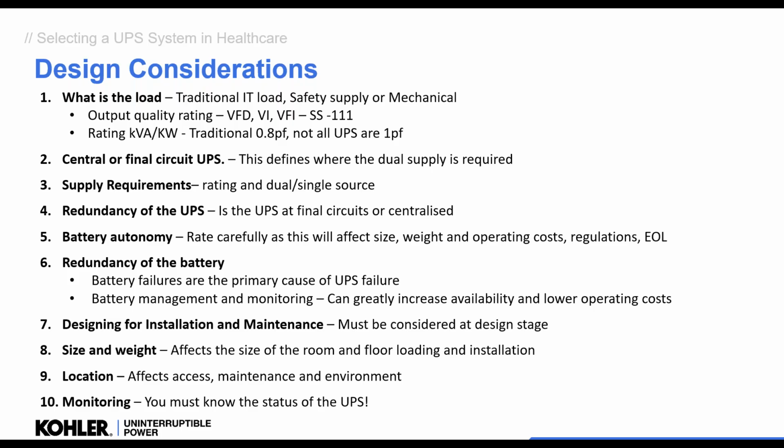The UPS will last 10 to 15 years in a good environment, but we must be able to get to it to maintain it. Okay, the size and weight of the UPS makes a big difference when we're looking at the installation, especially the batteries, which can be extremely heavy. And then we've got to make sure that that location is safe for everybody and the environment is correct.